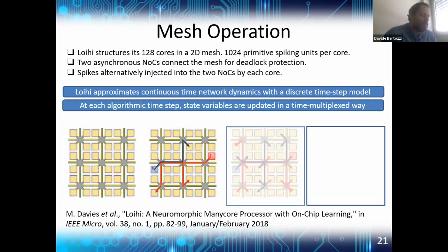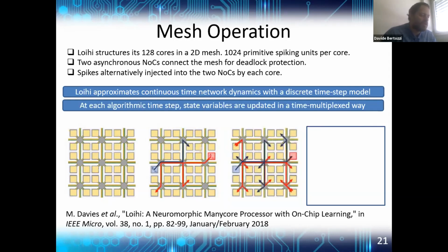Now, as time goes on, additional spiking distributions from other firing neurons add up to the network on chip traffic. You can see, here we start adding up the traffic from firing neurons throughout the entire platform. The network is distributing these spike messages with address event representation, in this case according to an X and Y algorithm. So spike messages are routed first along the X direction and then along the Y direction.